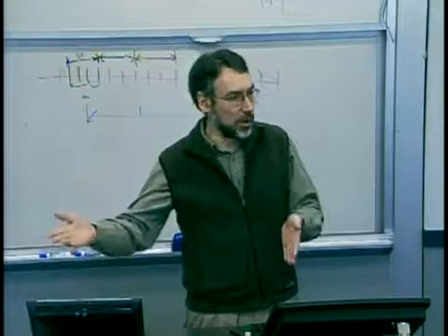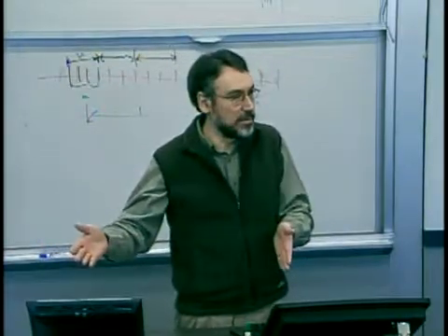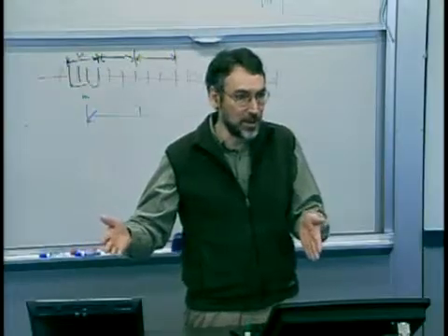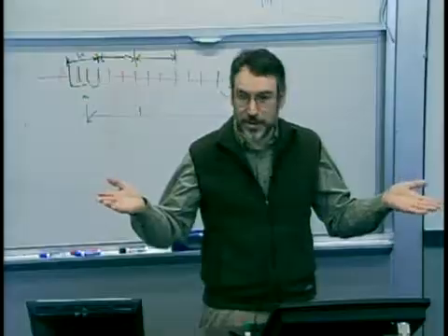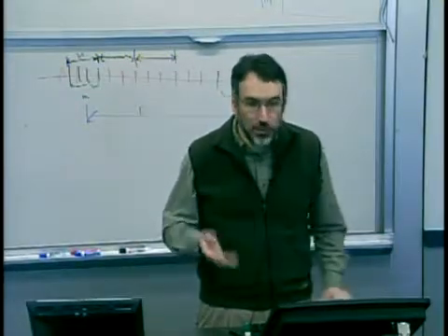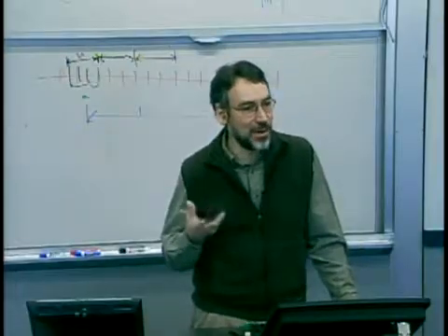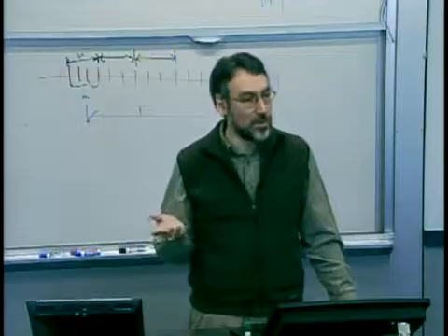And the point here is that once we've got a distribution like this, based on historical data that we use to build our control chart, we basically have a model of our process, right? It's a very simple statistical model that says it has a particular mean and it has a particular variance in the normal distribution case. And an important thing that we can do with that model is answer a couple of key questions that really come up a lot, like, how good is the process?